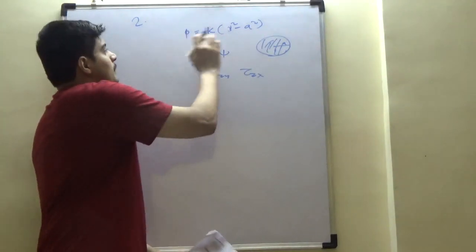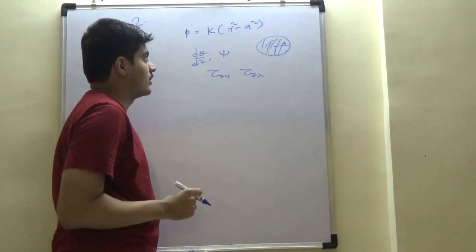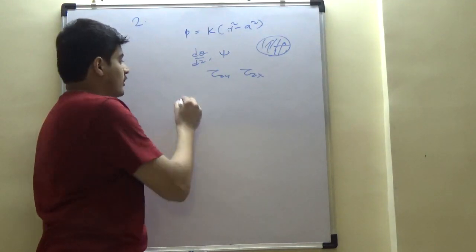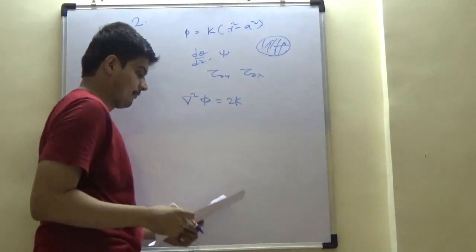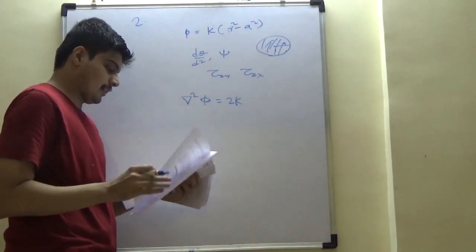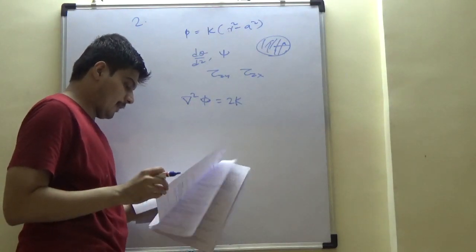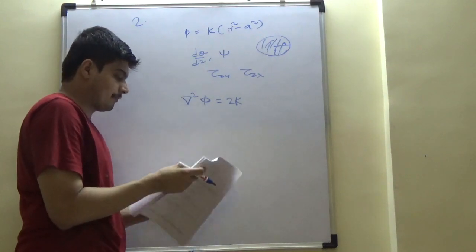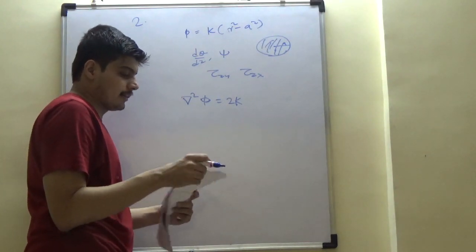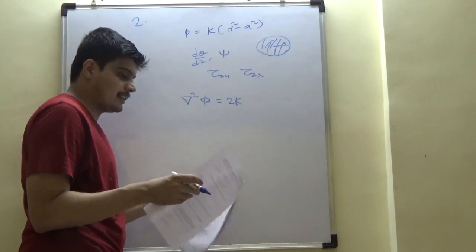Now implicitly, I know the second order magnitude is going to be constant, 2k, right? So del square phi is going to be 2k. Not a big deal. I already know it. Now the further thing I know is that I have to look at this in a way such that I can find GJ theta dash.